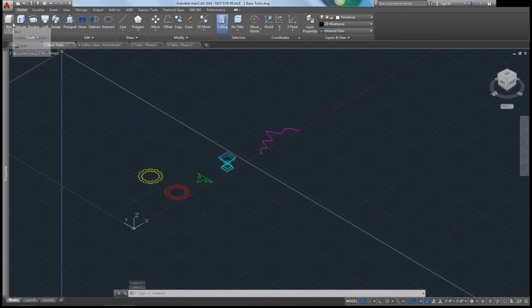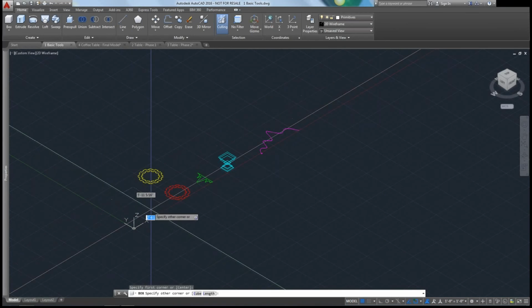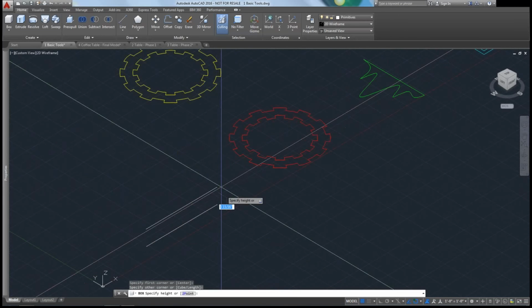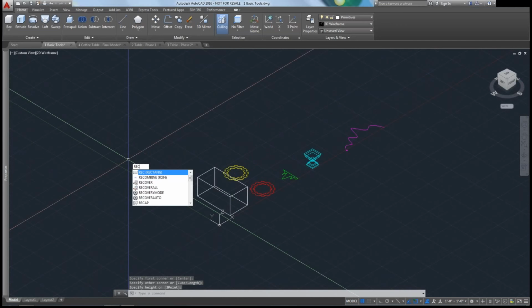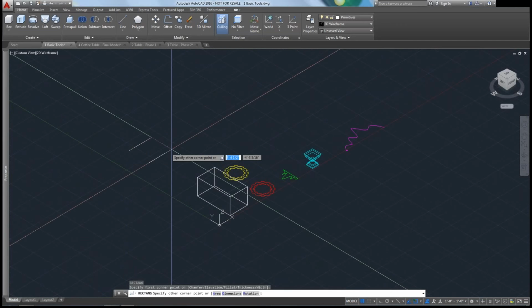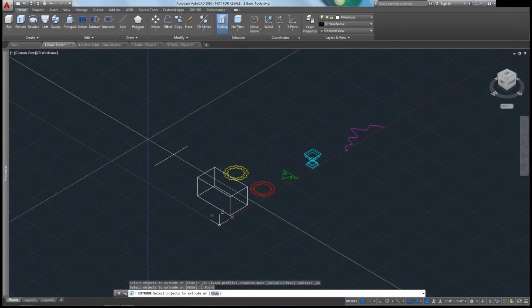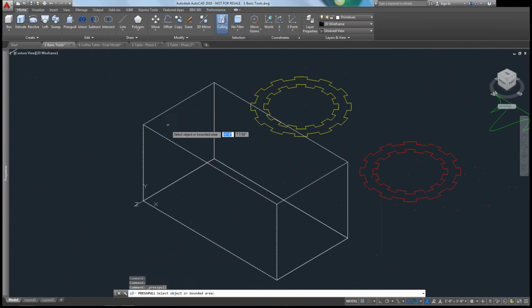So extrude, I'll use one of the commands that Victoria had shown earlier of a box. Now what extrude can do is if you just have a single rectangle, it's going to bring it up in one direction or another. What press pull allows you to do is to grab specific faces. See how these faces are highlighting?